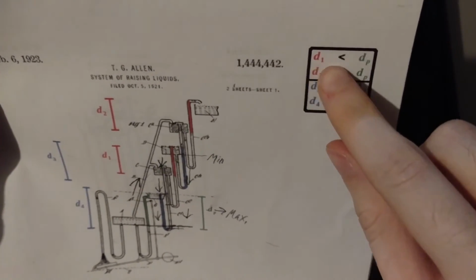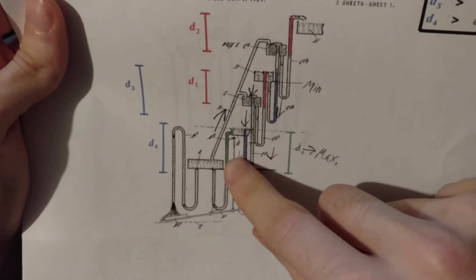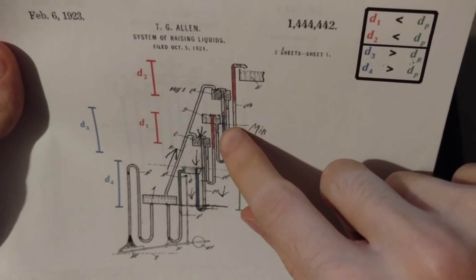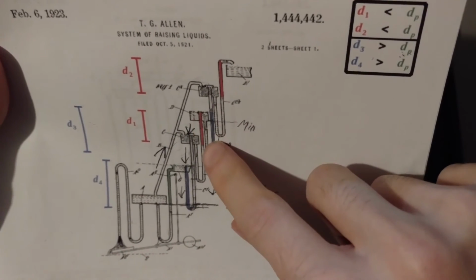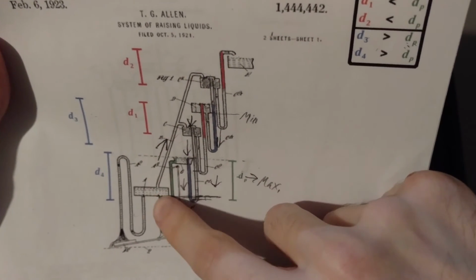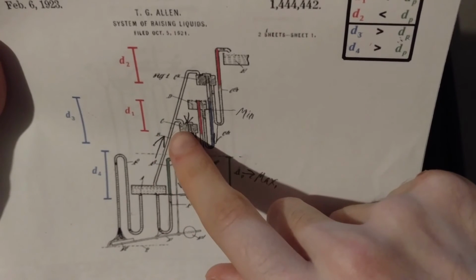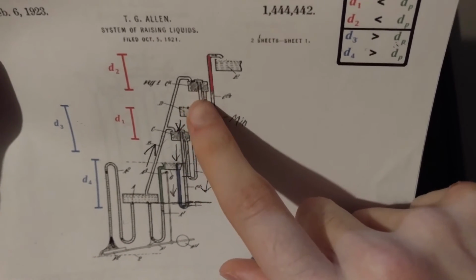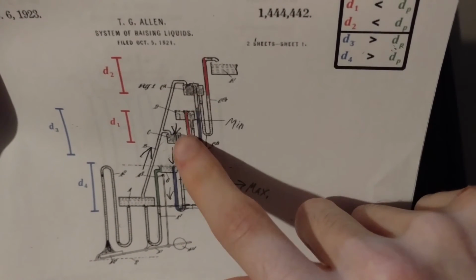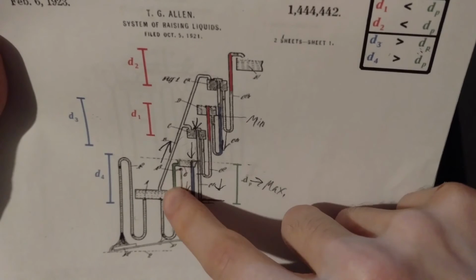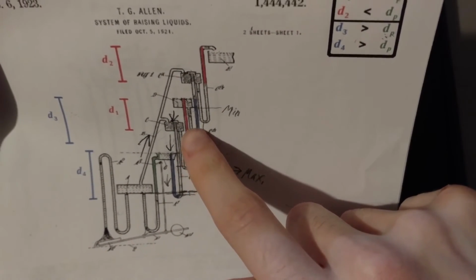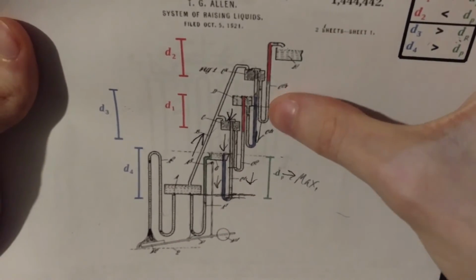As you can see, they have to be less than the distance or the pressure generated from the operating tank, of course. So in other words, the back pressures generated from these red sections here have to be less than the green one here. The reason being is that as the pressure is pushing up into these two closed tanks, which are now shaded, basically to show that they're filled with water, this tank here and this tank here, when the air is being pushed up into those tanks, it's pushing the water down and out and up into those tubes that have the red markings on them.